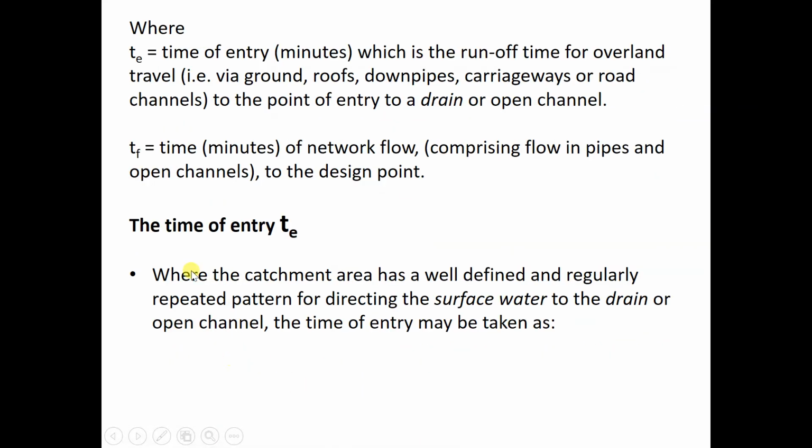So the TE is the time of entry. Okay, the runoff time for overland, from let's say the ground, from the roof, to the point of entry to the open channel. So usually from your roof, from the property, from the lot, a subdivision, how long will it take to go to the entry point? Usually it's a catch pit. Along the road there's a catch pit. The water can go into the stormwater pipe.